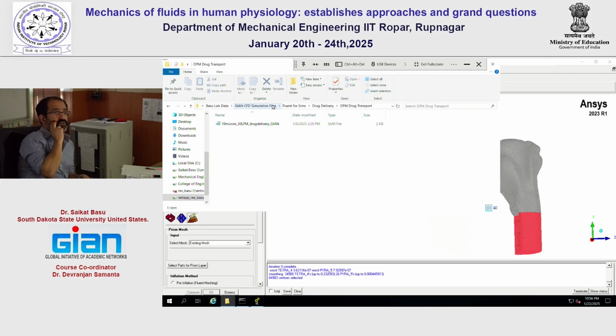Now you can figure out what the shape factor could be for whatever shape we are trying to track. But then again, there is this limitation: that shape would get fixed. It would not deform because that is not supported under the inert particle tracking. It is a rigid particle with just a different shape factor, basically.